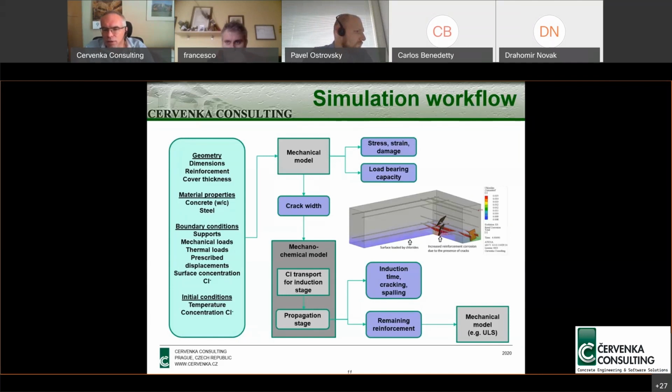So we can use existing models to determine that now the spalling must have occurred. So the spalling actually is not modeled in ATENA, but we know that there is a high probability that spalling occurred. So we can increase at that point the rate of corrosion.